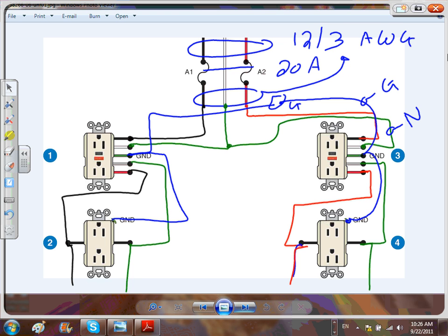And the last thing I want to mention right underneath it, guys, 406.13, 406.14, they expand the use of tamper resistance. Some of you look at me and say, Chad, well, I work at Hunt Electric and they don't do residential. Take this. If you go do guest rooms, hotels, motels, casinos that have hotels, motels in them, all the places, guest rooms and guest suites have to be tamper resistant now. Now we're getting into more commercial.